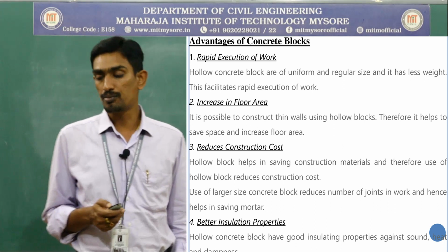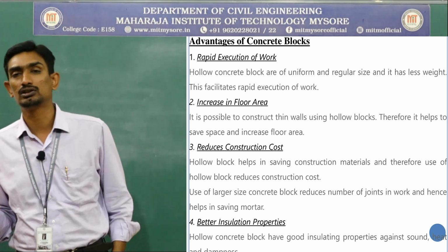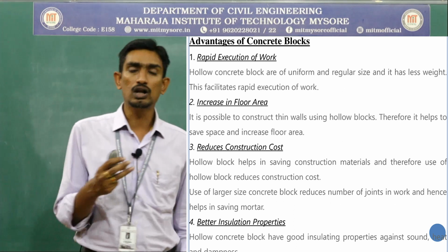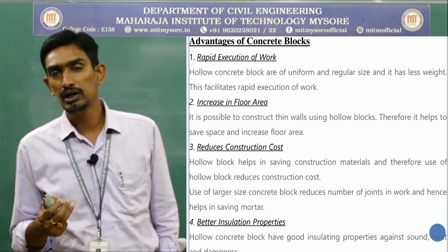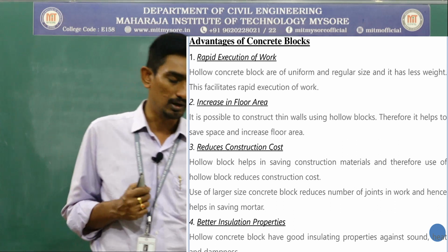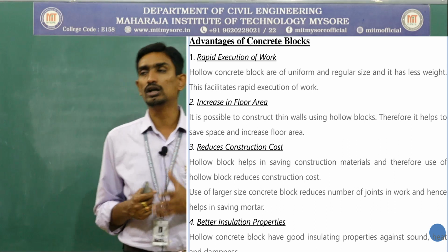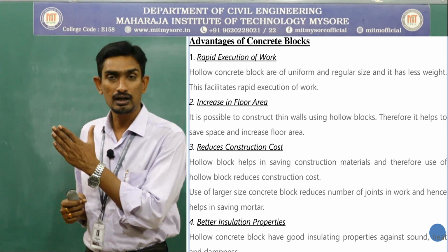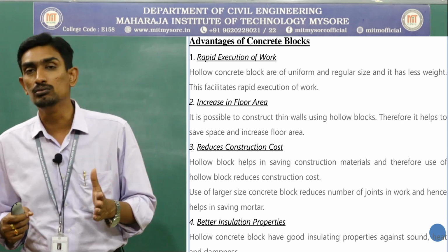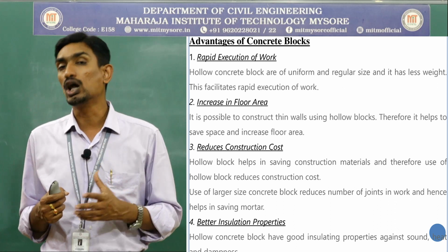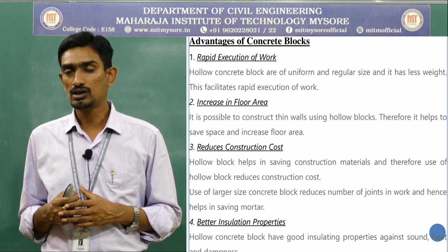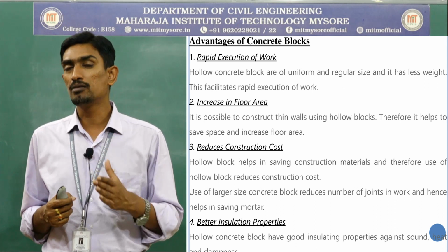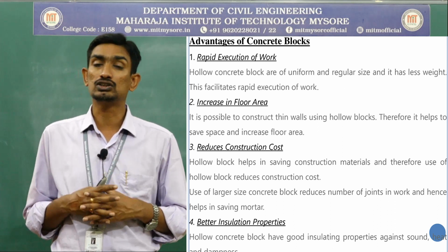Next, better insulation property, especially in hollow concrete blocks, because the more the hollowness, the better the thermal insulation property. For example, if you construct a wall with a solid concrete block, the heat that will be dissipated inside the room will be more compared to the hollow. Is it clear? So that's why you prefer hollow concrete block rather than solid.